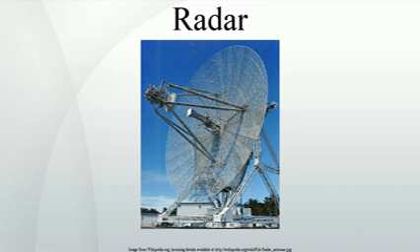Interference. Radar systems must overcome unwanted signals in order to focus only on the actual targets of interest. These unwanted signals may originate from internal and external sources, both passive and active. The ability of the radar system to overcome these unwanted signals defines its signal-to-noise ratio, SNR. SNR is defined as the ratio of a signal power to the noise power within the desired signal. It compares the level of a desired target signal to the level of background noise, atmospheric noise and noise generated within the receiver. The higher a system's SNR, the better it is in isolating actual targets from the surrounding noise signals.